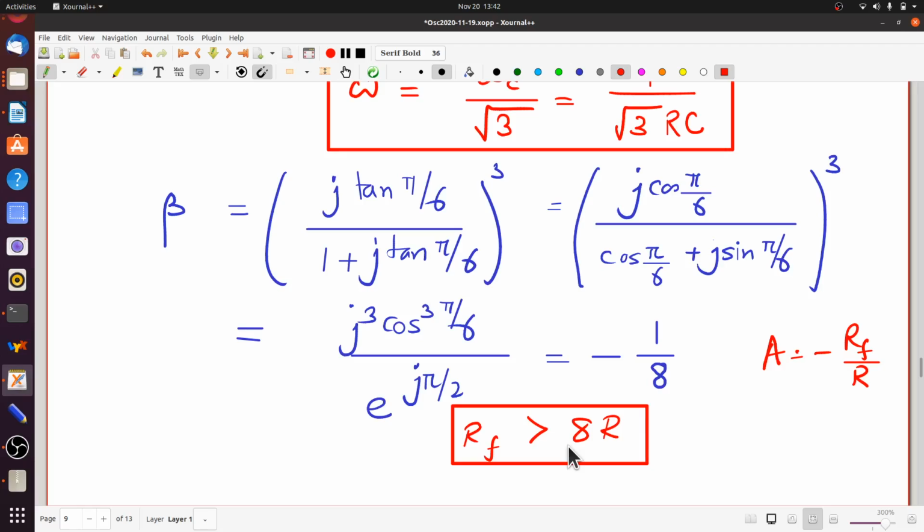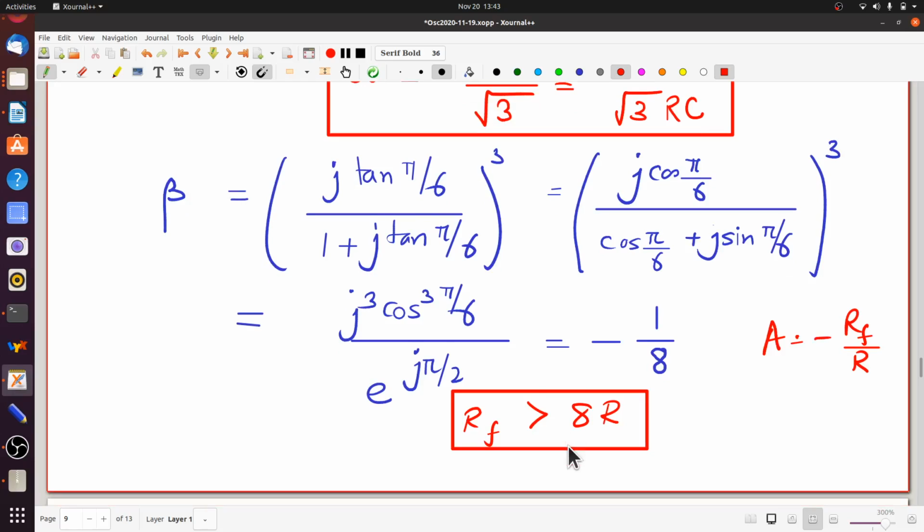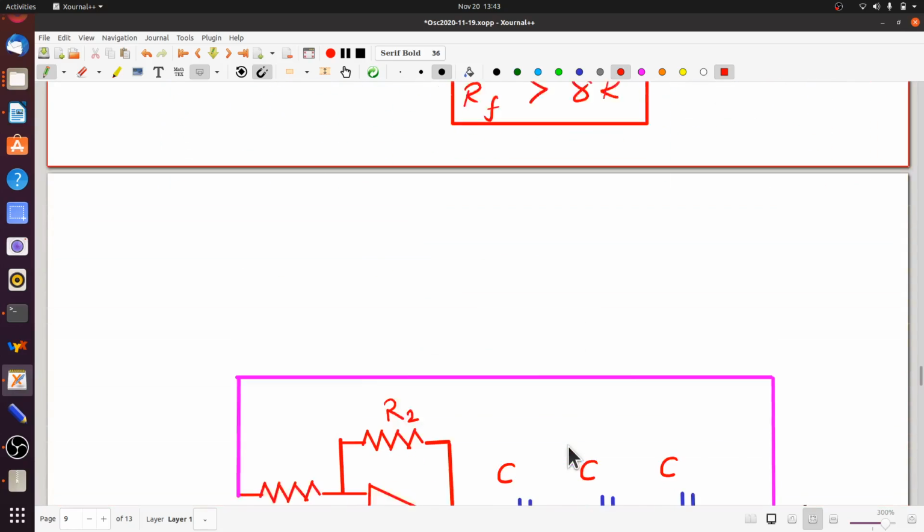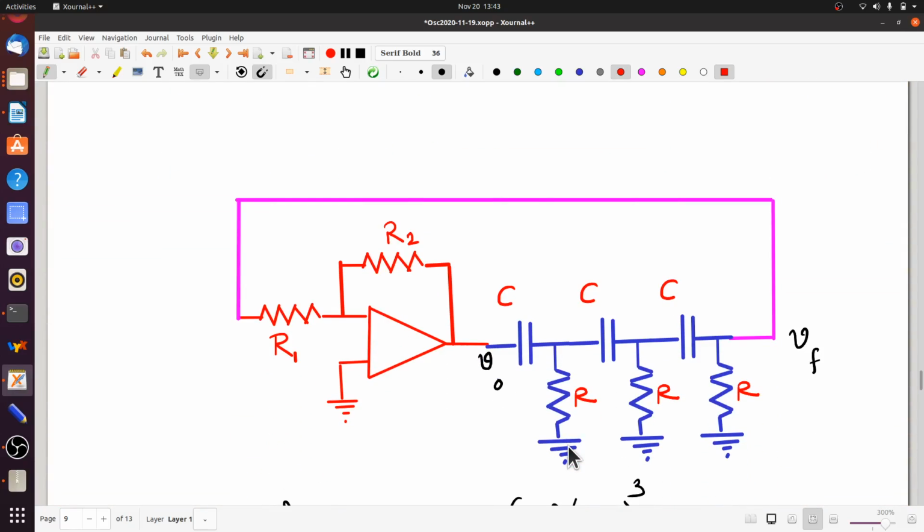But you have to notice that all we did was we had a 180-degree phase shift because of the inverting amplifier. We put in enough RC pieces to shift the phase back to 360. Well, we could have dispensed with the unity gain buffers in between and just used CR.